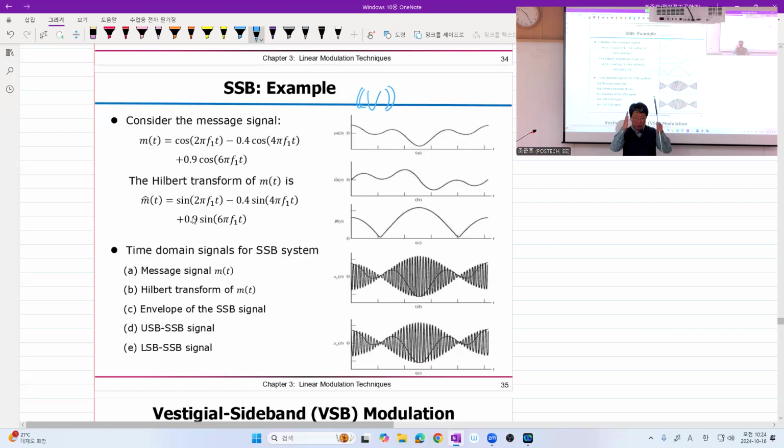Because if you have a real valued message signal, and you multiply by cosine something, actually you waste half of the spectrum, as we've already seen in DSB. We have 0 times sine 2 pi fct plus theta. So in modern digital communications, not only does the signal have the in-phase component, it almost always, not always, almost always has a quadrature component, which means that our message signal is complex valued in modern digital communications. So never forget that. Never get confused.